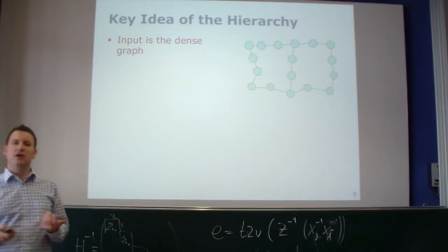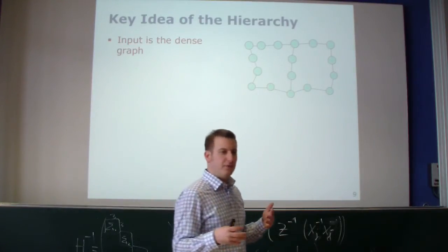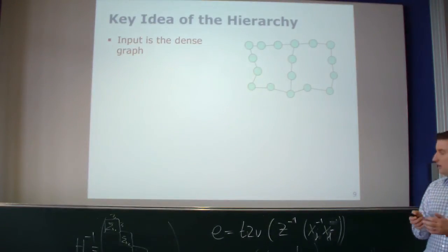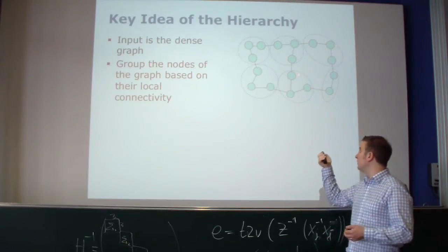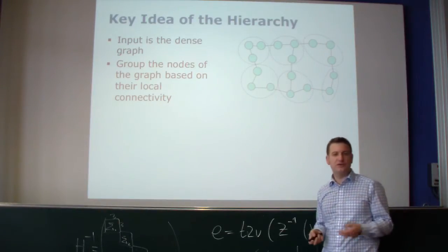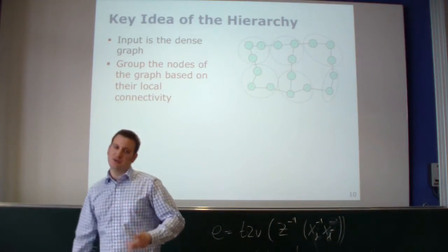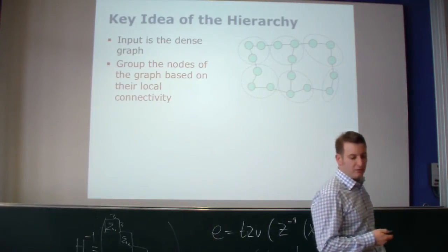The first thing we do, as I said before, is we need to form local groups. So we group nodes. We do that typically based on their connectivity. So maybe these could be our groups. All these nodes which are close to each other, or which the robot traveled subsequently while moving through the environment, I may form into these local groups.